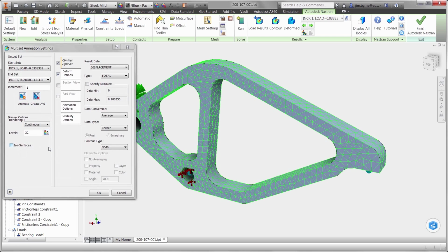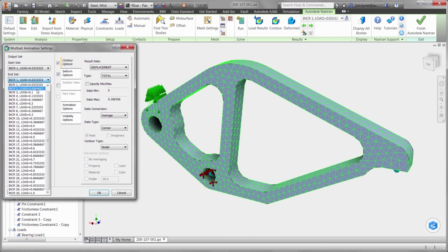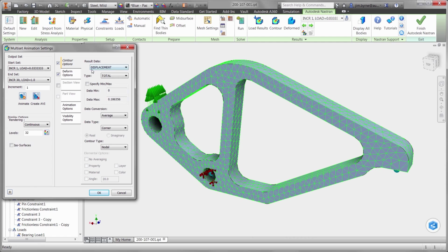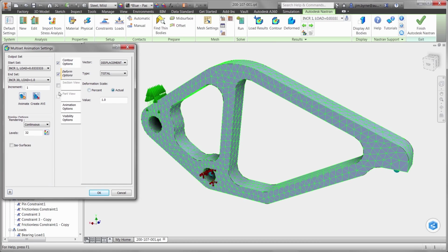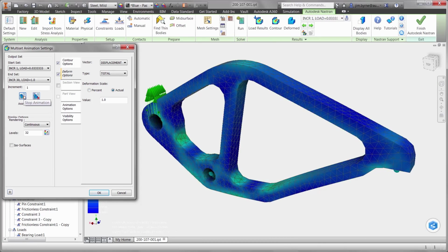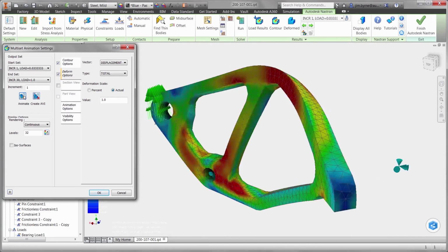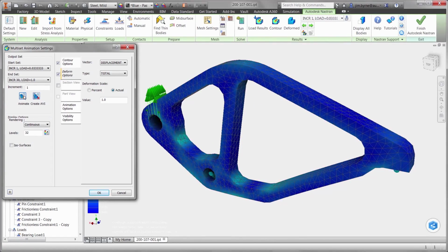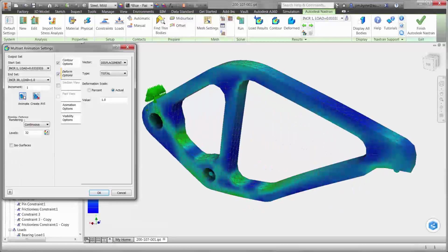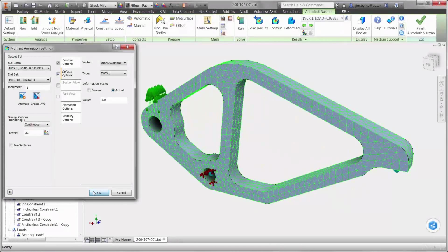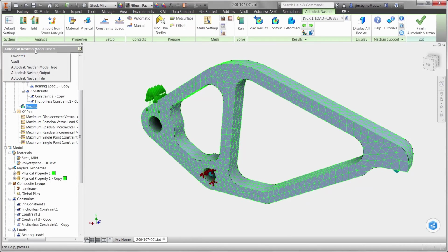Animations of the results may help to understand the weak points in the design for changes that need to be made in the model. We know that the design becomes unstable at 1600 newtons. By watching the animations, we can make better informed decisions for improvements to the stiffness of the geometry. Based on these results, we can confidently move forward with the model using mild steel. Using these types of studies, we can fully understand our design and run several what-if scenarios with various materials.